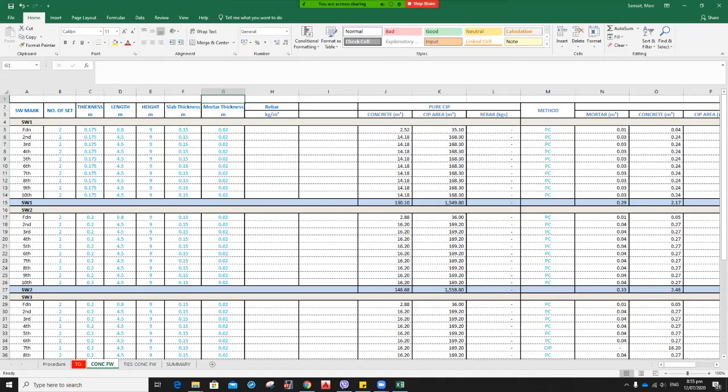Okay, then we have a rebar tab. Basically, this rebar tab is editable, meaning it depends on the level of information present. Later we will go back to the rebar tab. So we just go first to the concrete and formworks. Concrete is basically the volume. Then we have the cast in place area, or the CIP area, which is the formworks, if we do it in cast in place. Then definitely the rebar, which, as mentioned, we will go back to.